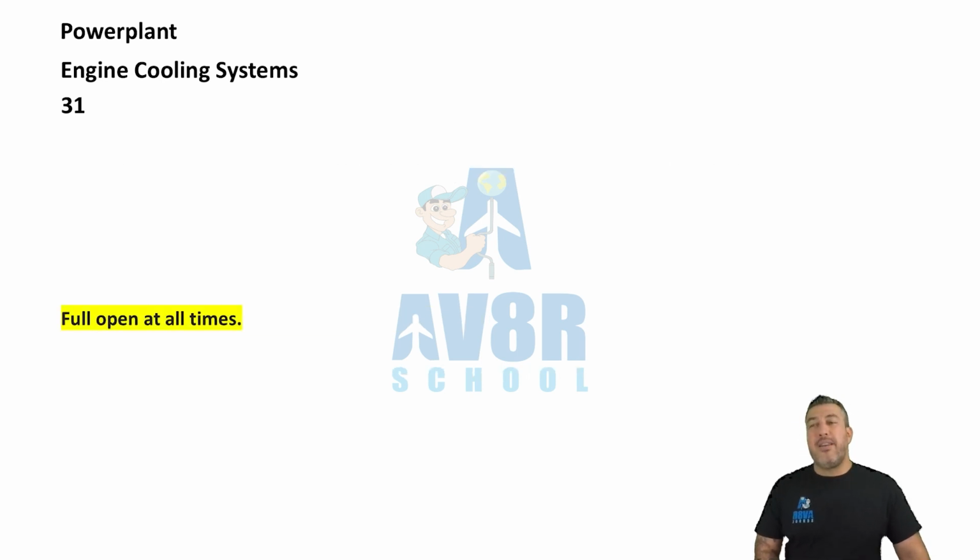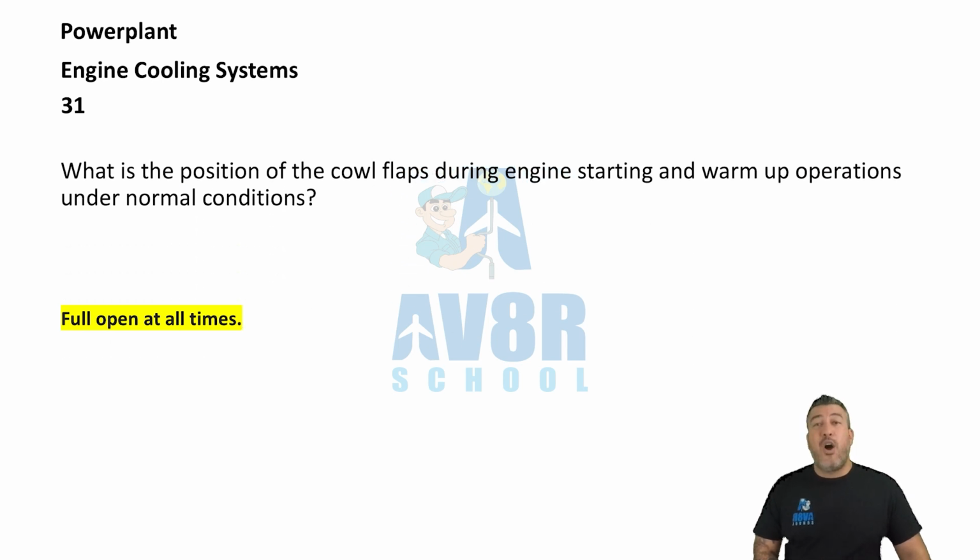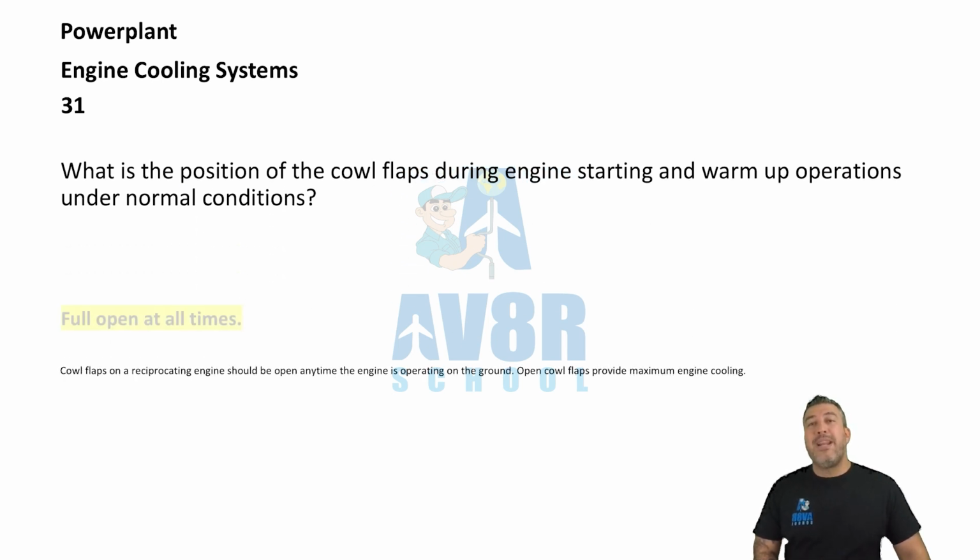Number 31, full open at all times. What is the position of the cowl flaps during engine starting and warm-up operations under normal conditions? They should be full open at all times.